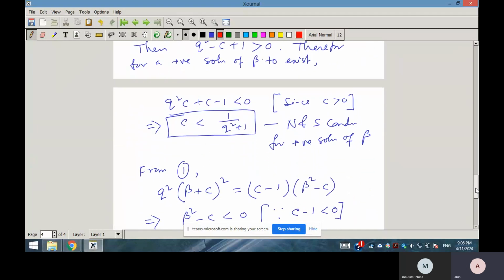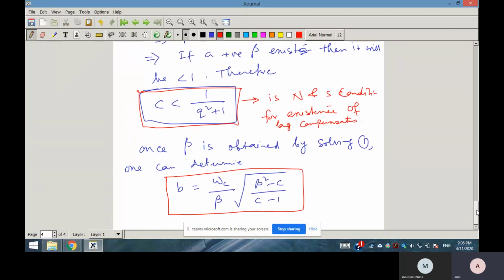Phase lag is not desirable, but we have to accept that it will provide it. Ultimately the overall compensated system phase margin can be improved, because it is lowering the gain curve, so the gain crossover frequency will decrease. So although it provides some phase lag, overall phase margin will increase.